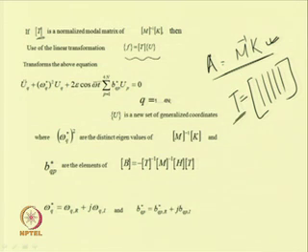If we are using T as the normalized modal matrix and taking f equal to T into u, that means we are transforming the coordinate from f to u. Then we can write the original equation in this uncoupled form, that is u_q double dot plus omega_q star square u_q plus 2 epsilon cos omega bar t into summation p equal to 1 to 4n of b_qp star into u_p equal to 0, where q equal to 1 to 4n are the 4n generalized parameters which depend on the modes of the system. So, u is a new set of generalized coordinates we are using here.